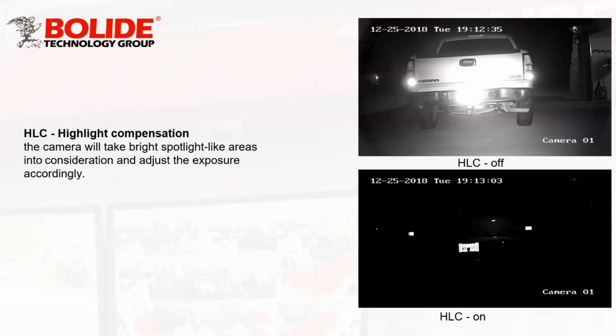Highlight compensation, HLC. The camera will take the bright spotlight areas into consideration and adjust the exposure accordingly. So this is very good where we have license plate cameras. You can see in this image, sometimes with the IRs on, you'll get that bounce back, especially off the license plate. In this picture, you can't see anything; you're getting some whiteout. Turning this function on will allow you to lower the sensitivity of the IRs, or actually the image, and bring that clear picture through. So that's the HLC.